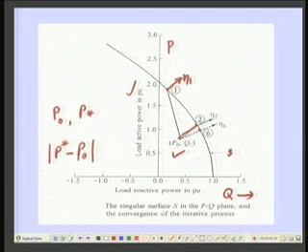Then at this point 1, since this point lies on the surface which represents the unstable operating condition, you find the normal at this point. Now you stretch in the direction of the normal, and you keep doing this till you get the minimum distance.